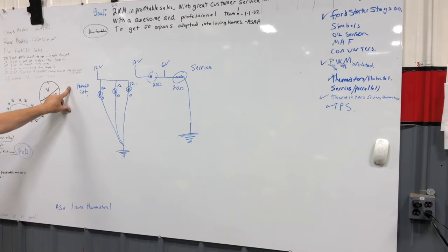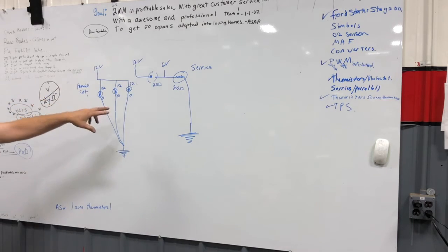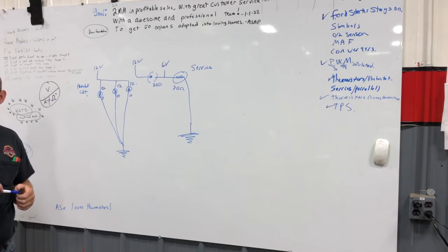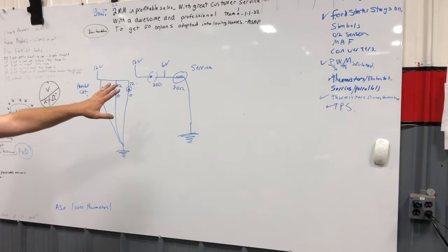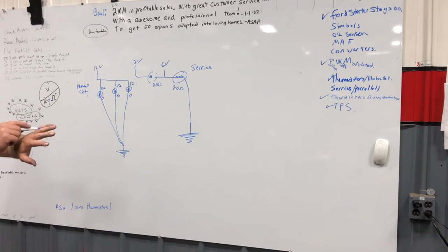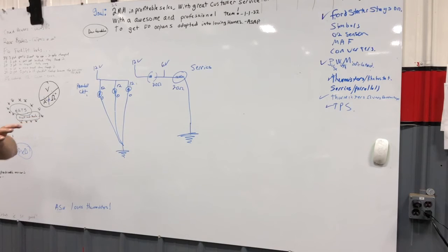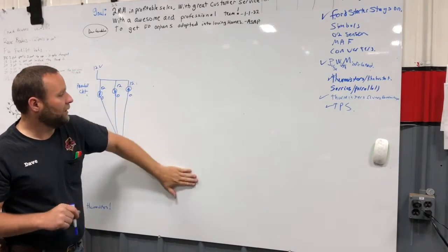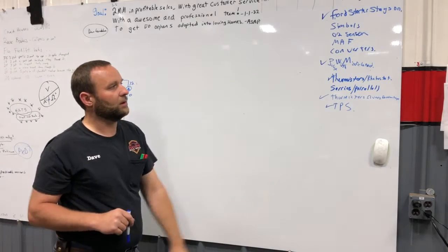There are more resistors in series than there really are bulbs. The only thing I can think of that did this was the cooling fans on a Chevy Venture. The diagram has three relays and runs this one plus this one to make a series, and all the relays have five terminals instead of four because they have to use the backside of them. It has to shut and then it has to work. So you can have bad relays, it was complicated. So they basically did away with most of this. That's hardly ever in a car anymore.